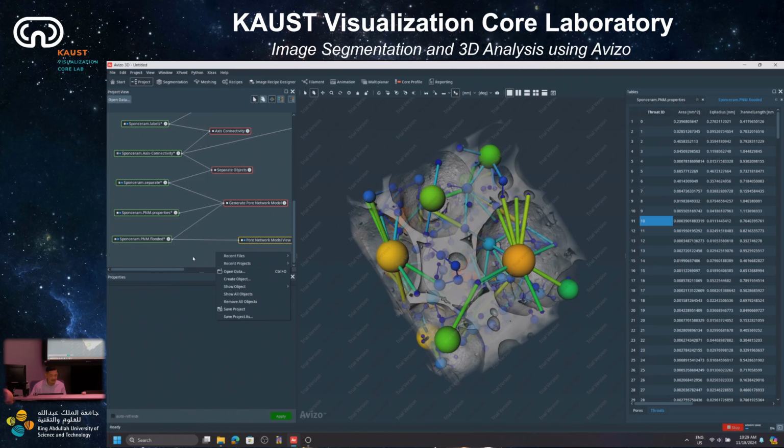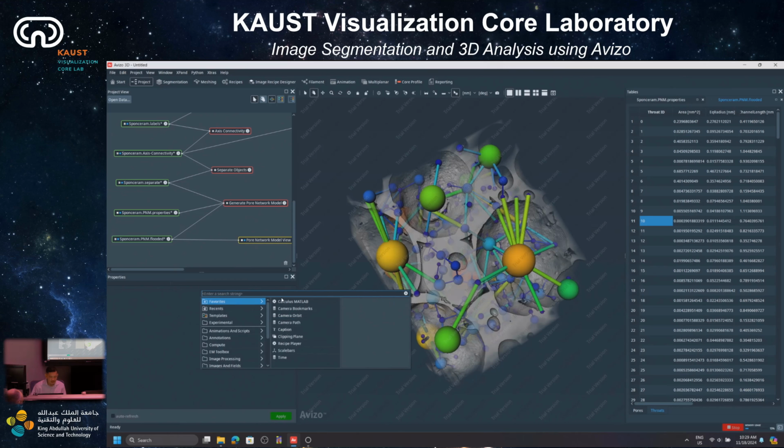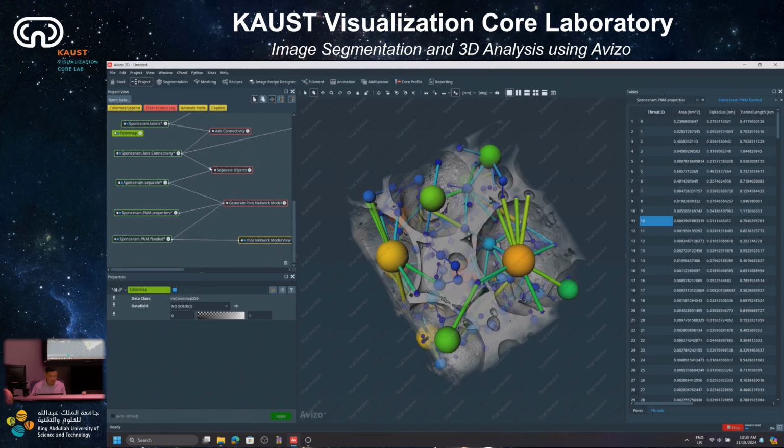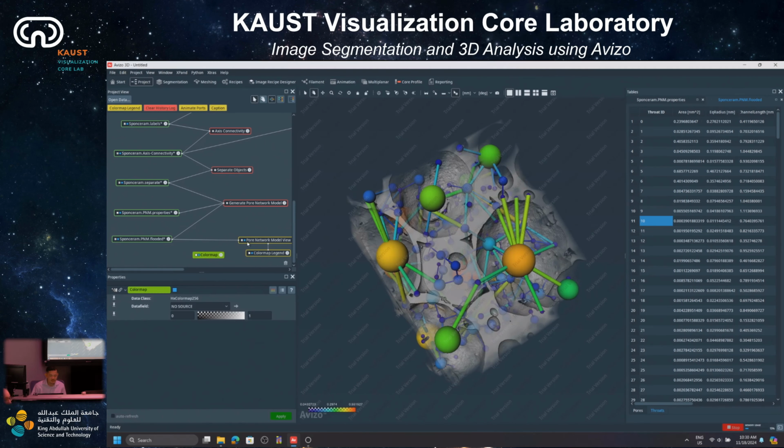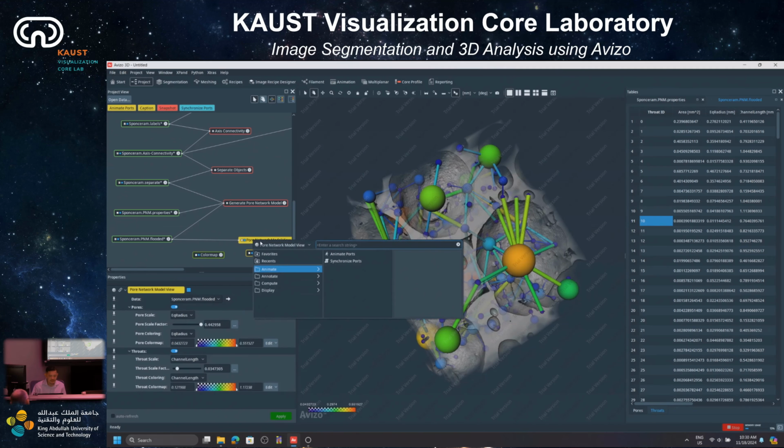We right click in the empty space somewhere and select create object. Then you can type color map from the search box. When the color map comes up, as Ronell suggested, it's color map legend. It might be a bit of a bug as well, and then I attach the color map to this point, because usually it should be able to directly search for color map on this kind of point.